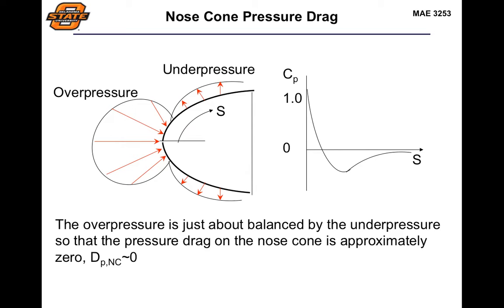Now this is very similar to what you have on the leading edge of a wing. You have a stagnation point, so you end up having an area of greater pressure due to your reduced velocity. As the flow starts to accelerate over the curved section, you end up having a pressure drop.